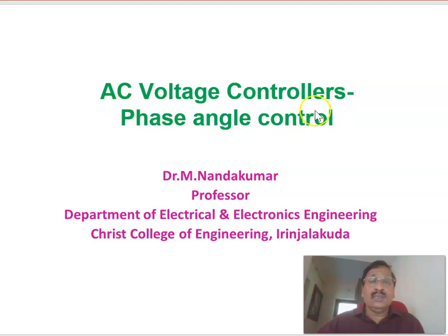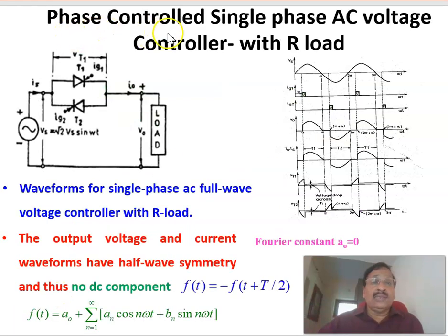In this presentation, I'll be explaining AC voltage controllers, that is, AC to AC converters, and the control technique used is phase angle control. Now let us look at the phase control single phase AC controller with resistive load, that is, R load. And this is the circuit topology in which the input is a single phase AC supply